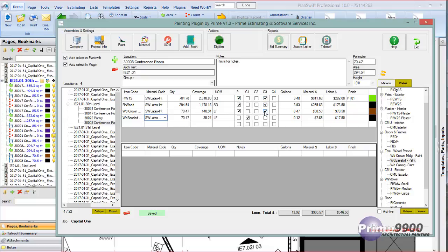Now this selection here is made when you build your library item and brought forward to the project to satisfy the requirements of pricing. Now if for any reason the project might have changed, you can come in here and change the number of coats. You'll notice that parametrically the numbers change over on this side and give you the different requirements for cost and for the gallonage required for that particular item. That can be done with any of these items that we've got here.